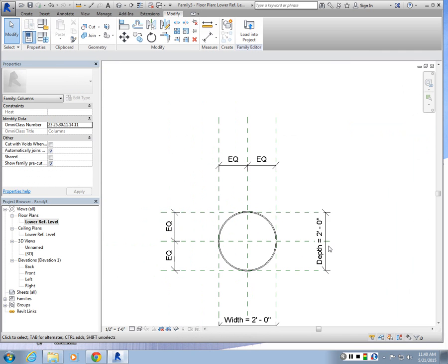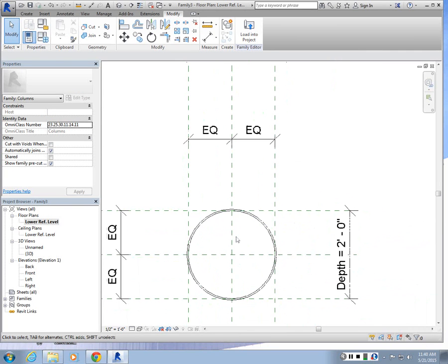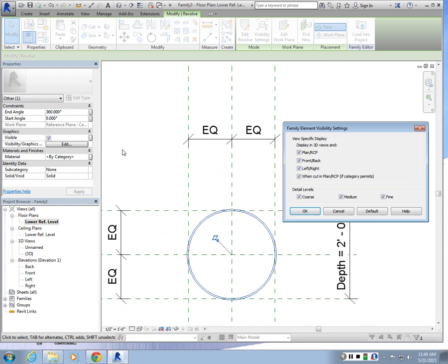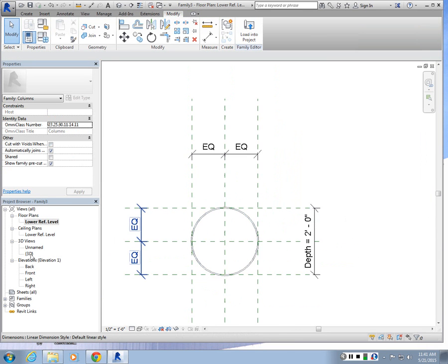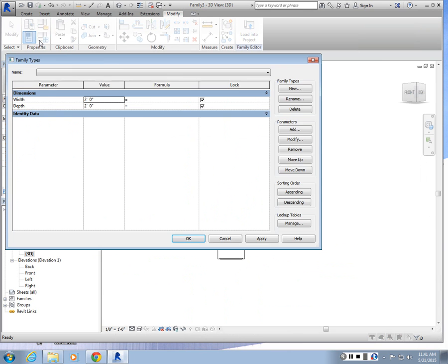So the graphic representation for this object, you could model any type of feature here, any type of detail, and then choose the three-dimensional object, go to visibility and graphics, and uncheck the plan view setting, because let's say you have a three-dimensional object that is tapering. You want to represent it graphically with a specific radius value. You can just model that radius here and then use that for the plan cut drawing, right? Rather than cutting the whole three-dimensional object itself. So we could uncheck these two. Hit OK. I actually want to do a bit of flexing to this to see if it's going to work.